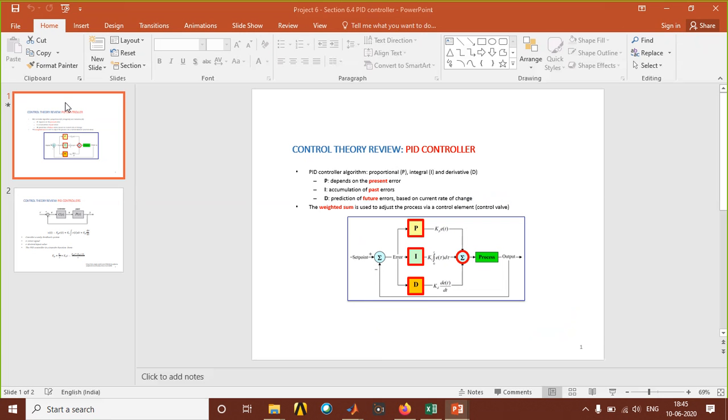So go through this. The first is nothing but a gain, the second is nothing but integration, then differentiation. Since we have Kp, Ki and Kd, which are all in multiplication, whenever a multiplier constant comes into play we are going to use gain, and I'm going to use my error term here directly.